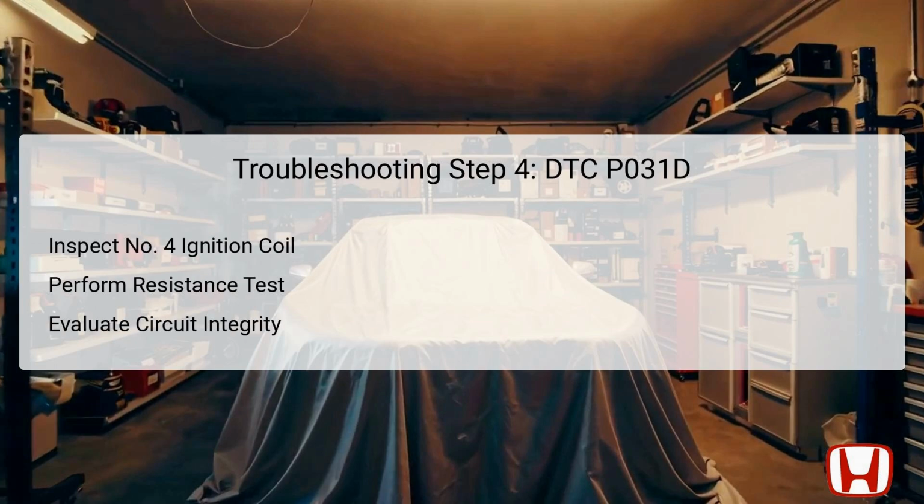To resolve DTC P031D, focus on the number 4 ignition coil and inspect it for any physical signs of failure, such as cracks or burning. Conduct a resistance test to measure continuity within the coil, as improper readings can indicate coil failure.